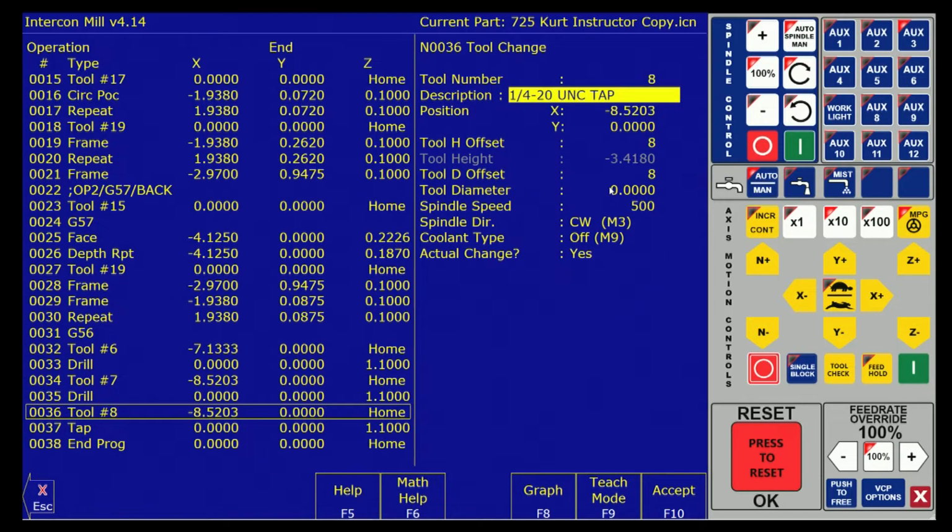The answer to that. All right, so this tool is the longest tool of these three, so I'm definitely going to the side to do this tool change. So definitely put a location off to the side in there. Tool diameter doesn't matter because I'm using it axially. RPM. You are not calculating RPM here. All right, let me take that back.